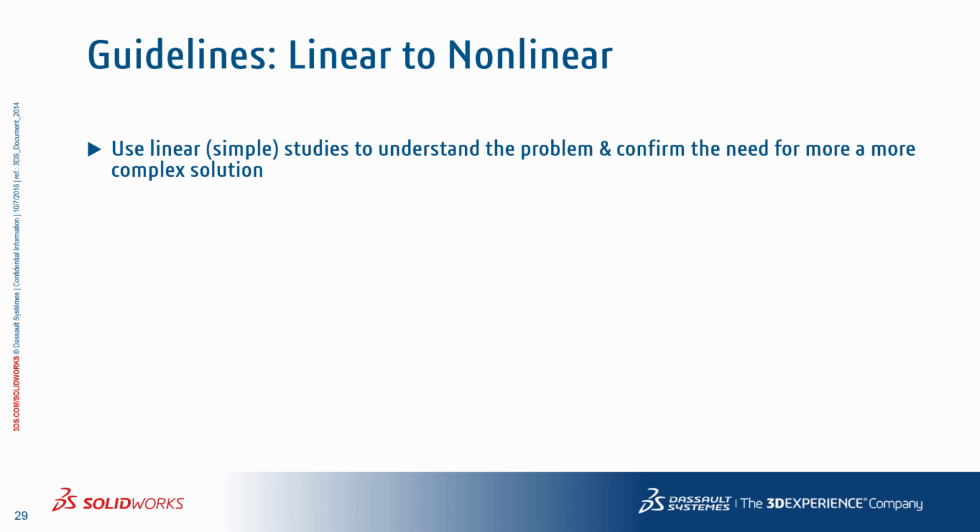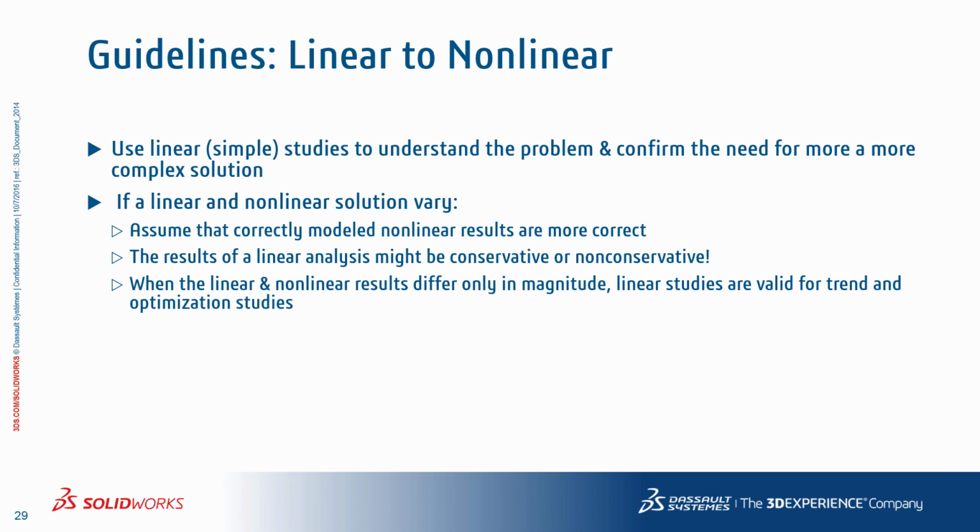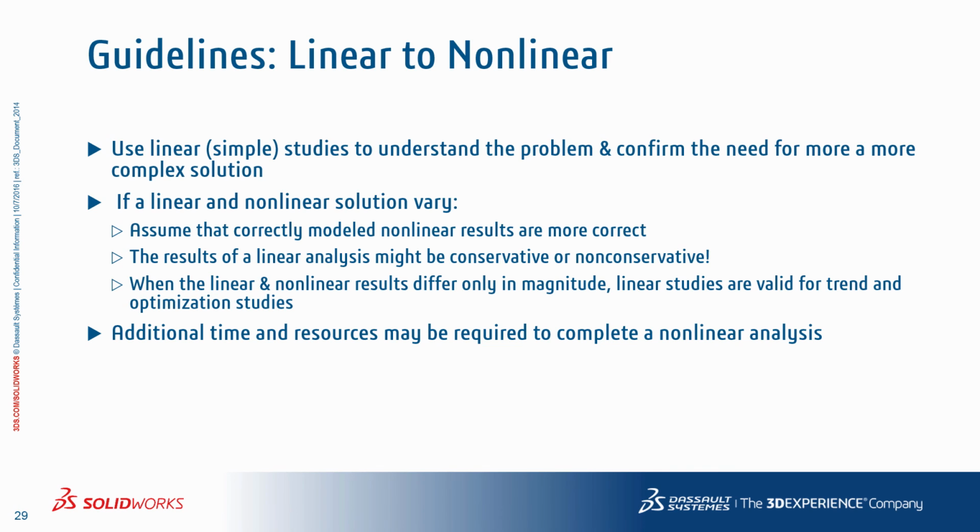Nonlinear solutions can take 2 to 10 times longer than a linear solution on the same mesh. So it is definitely worth validating loads and restraints faster with a linear model first. If the linear and nonlinear results are different, then go with the nonlinear results as they will be more accurate. Now, additional time and resources may be required to complete a nonlinear analysis.